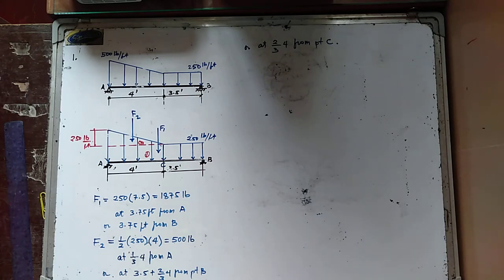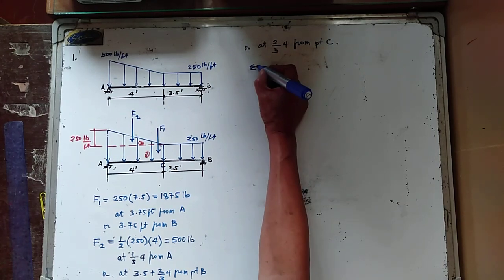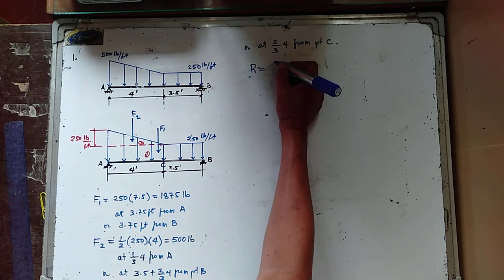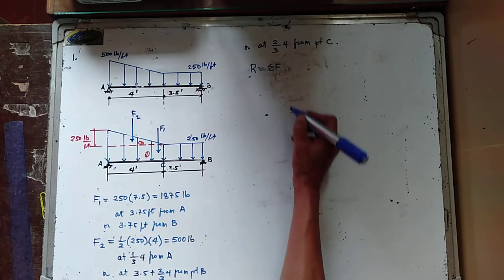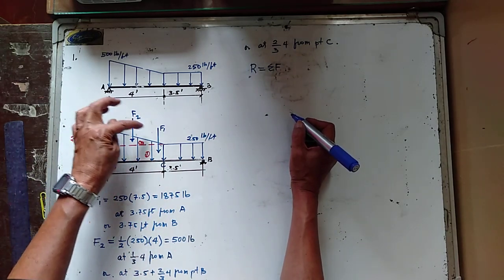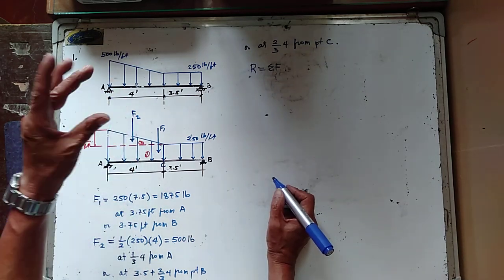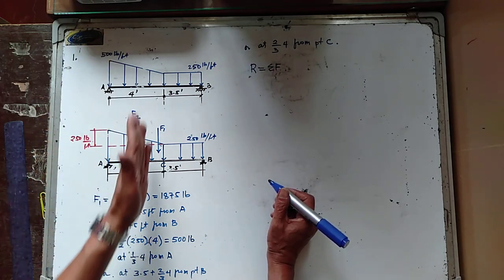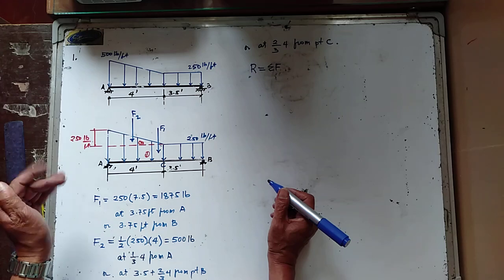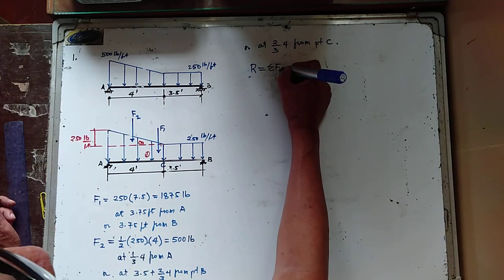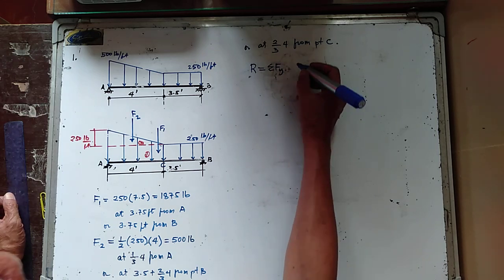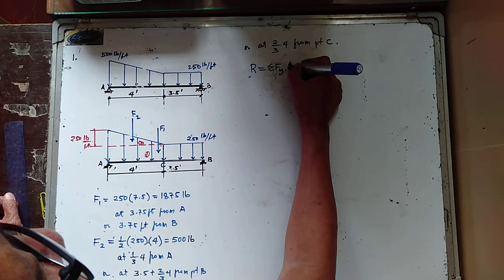Now, the resultant force is now equal to the summation of forces. Try to take note that the two equivalent resultant forces of the distributed normal load are directed vertically. So I'm just going to consider that one as in the y direction. So summation of forces in the y direction. I'm going to take upward forces as positive.